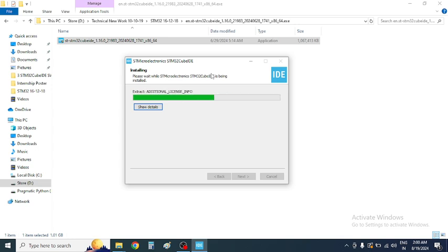We are using the STM32F103 C8 board, which is also called the blue pill board. It is low cost. You can use that board for practicing purposes. To download the program, the ST-Link V2 module is available, which you can use for program downloading and debugging purposes.